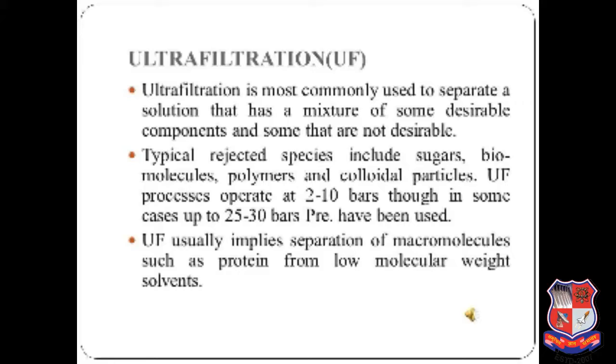The rejected species include sugar, biomolecules, polymers, and colloidal particles. Ultrafiltration processes operate at 2 to 10 bar, though in some cases up to 25 to 30 bar have been used. Ultrafiltration implies separation of macromolecules such as protein from low molecular weight solvent.